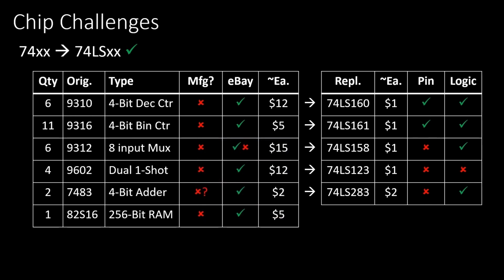These two adders are used in the vertical video chain to shift the image slightly on cocktail mode when player 2 is up. So if you're not going to be using two-player cocktail mode, then we should provide some onboard jumpers or something that allows us to bypass the flip logic and not have to populate these adders. As long as the reduced delay doesn't mess anything up. You never know. So the last challenge on this list is the bipolar RAM, which is used for brick storage.